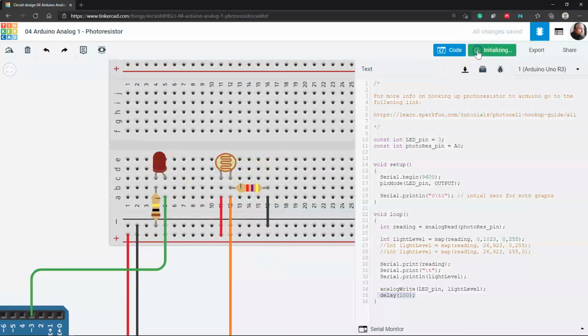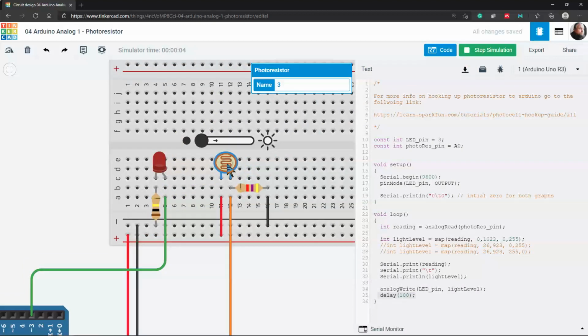So start simulation. Wow, we can see it's slightly dim, and remember now we have to click on the photoresistor here, which is dark, and if we increase this, we get a nominal increase and decrease in the actual LED. Boom, due to that resistor here. Maybe to make this a little bit higher, we'll change the resistance of that one so it's not bugging it so much. Boom. Come back here, so that's high. We go down to low, so now it's a little bit more noticeable. So it's changing that to a 1k ohm instead of that 100k I had.